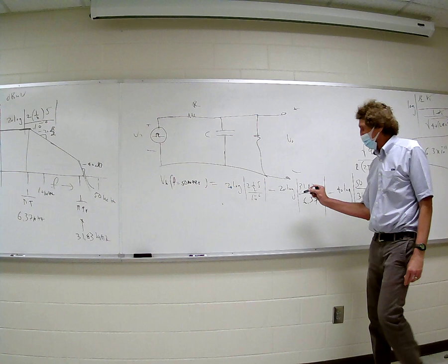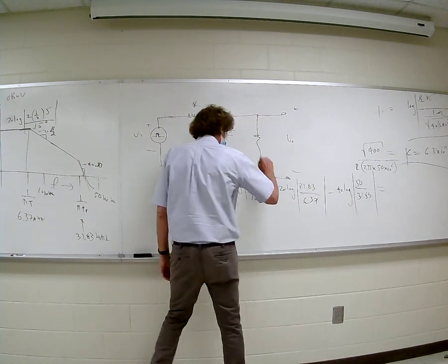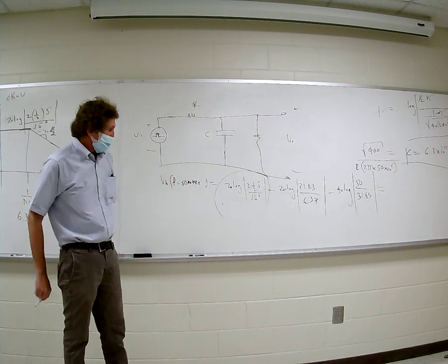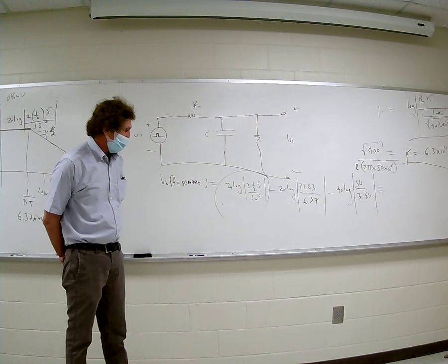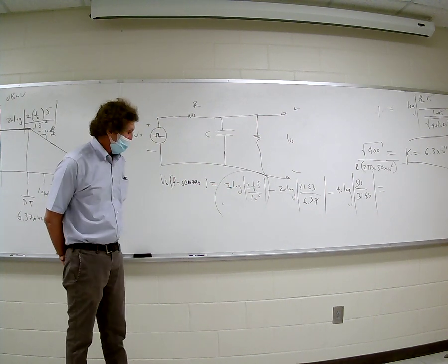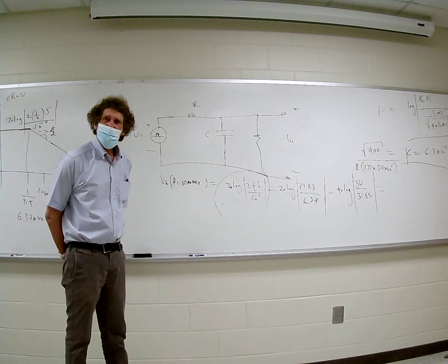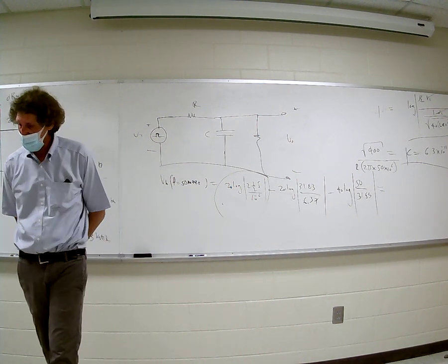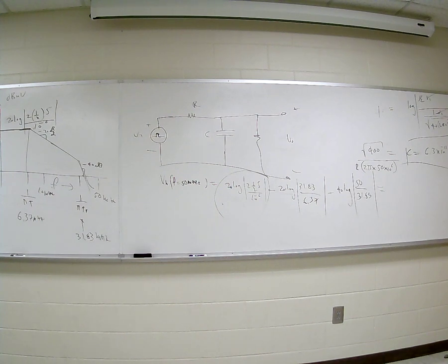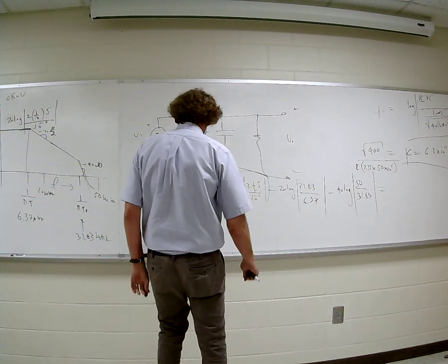Now, what's this? It's what? 5 over 10 to the minus 6. So 5 times 10 to the 6, take the log of that, times 20. Is it 136? What is it? Did you get it? I did it not in microvolts, I did it with just regular volts. No, give it to me in microvolts. Well, microvolts, I got 10 to the 6. 133.9. Yeah, that's about right. 133.9.